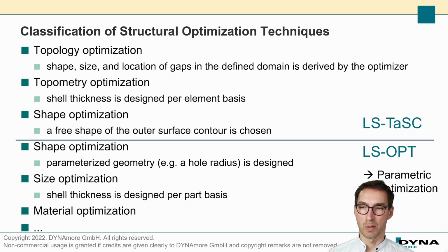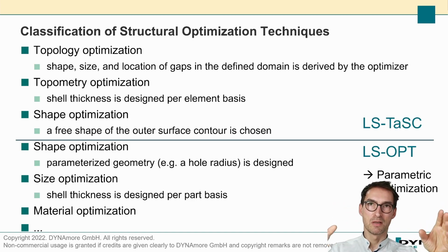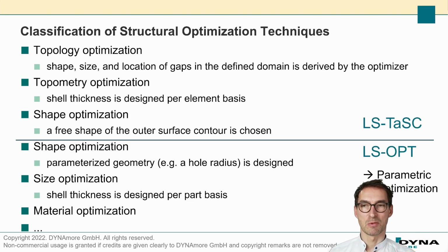That is one way. We can also adjust the shape. Let's say we have a curvature, but what is the optimal radius of this curvature? This is also a question, and it goes into optimization strategies as well. Or if you have a given shape, you may also parameterize it. Instead of having this free surface with many parameters, you may have just one parameter for the shape, say the location of a so-called reference node, which changes the slope or whatever. This is also some kind of optimization.